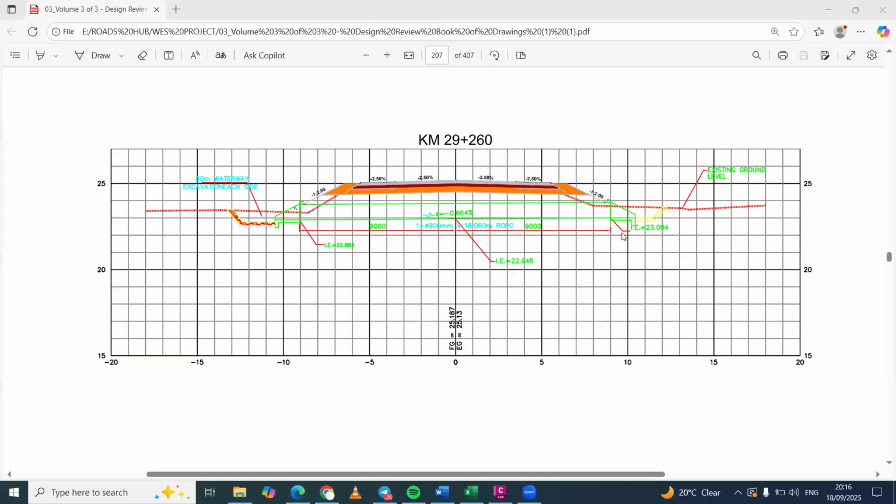Further away from earthworks calculation, we can visualize the design features in detail. Basically, we're essentially making a slice of the road. And it makes it easier for us to understand or compare the plan and profile. Plan and profile is not enough. We need to have sections of the road to be able to make out the rest of the details that plan cannot show and profile cannot display.